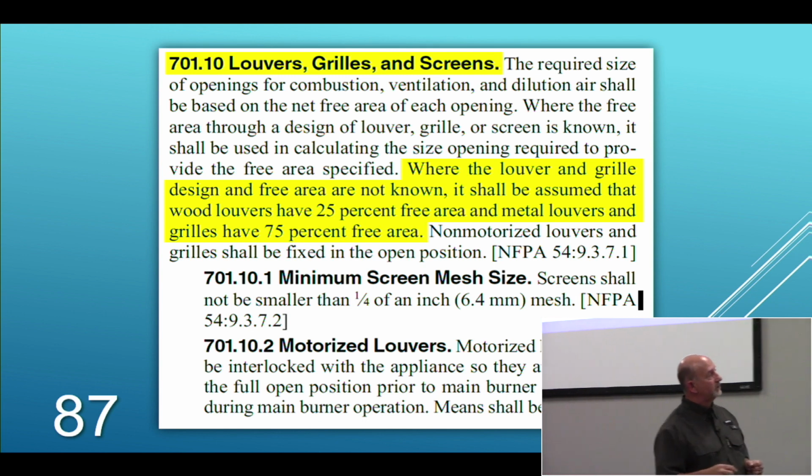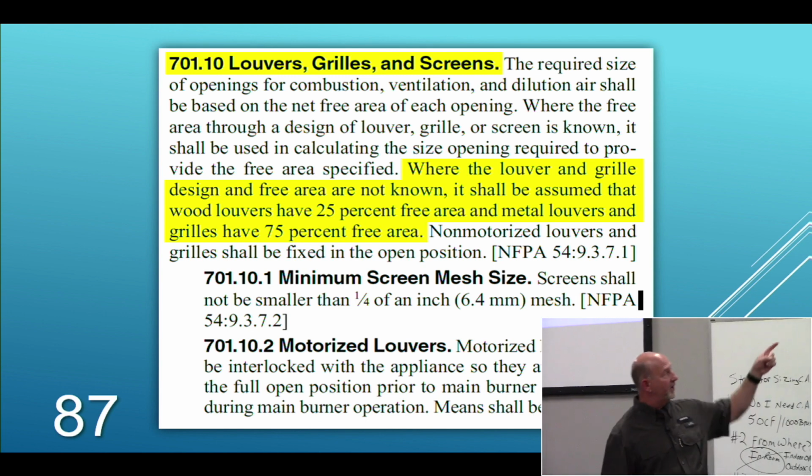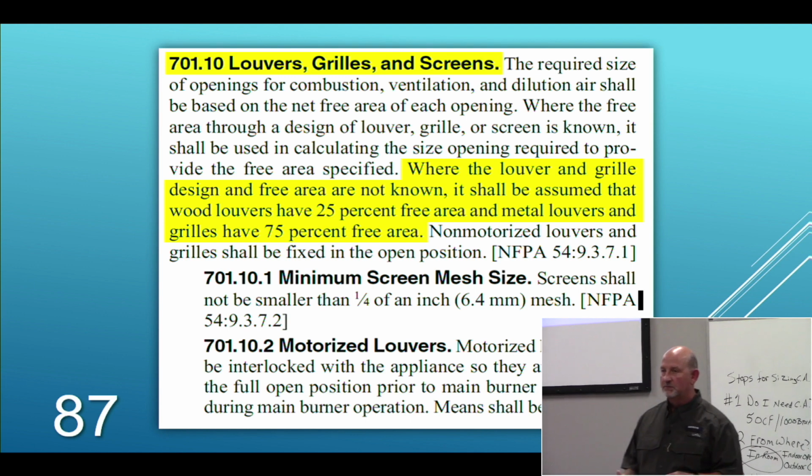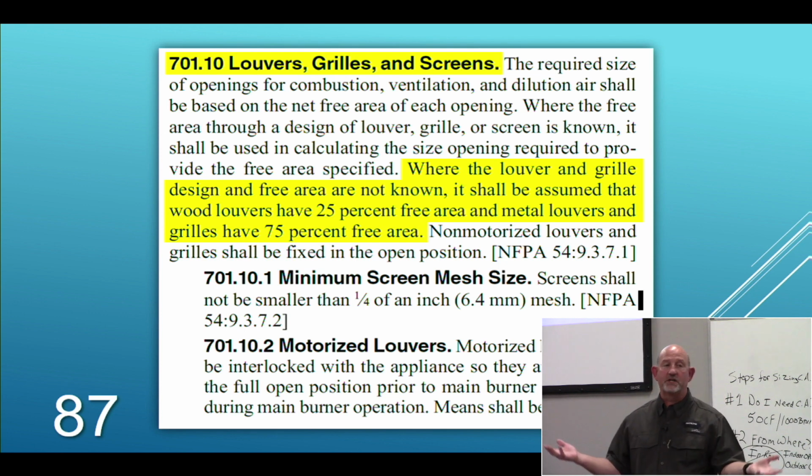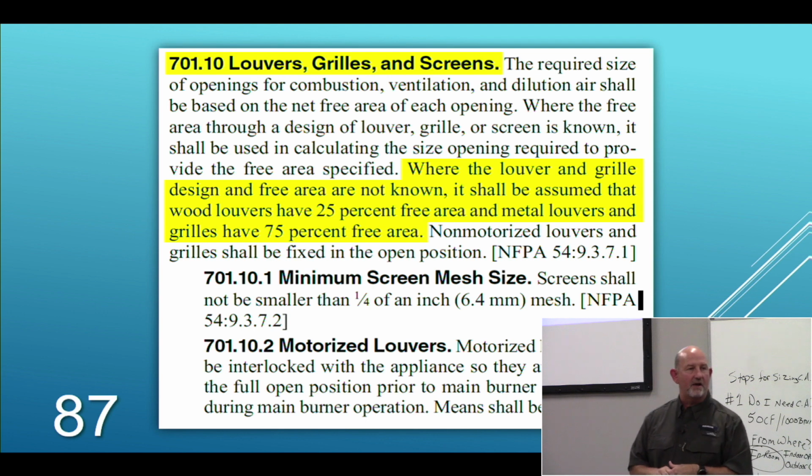Now, this could be either one, but do you agree these louvers and grills may or may not have a damper on them? Now again, code said no manual damper, so I'd have to use a louver without a damper. I'd have to use a grill without a damper. That way Wade couldn't climb up there and close that because there's nothing to close, right? These regular air vents you run into a residential house, for example, a lot of those have dampers on them, so they could close those, and if that's where the air is circulating through, we lost that, right? So again, we'd have to go there.